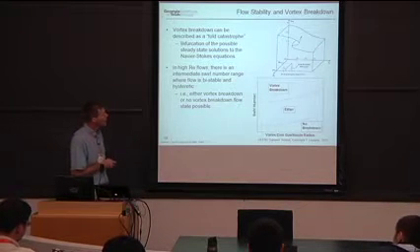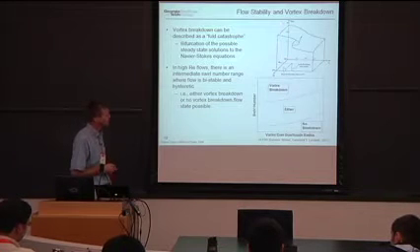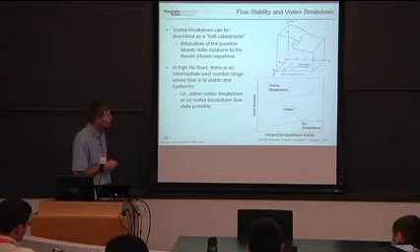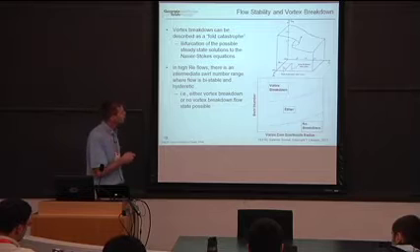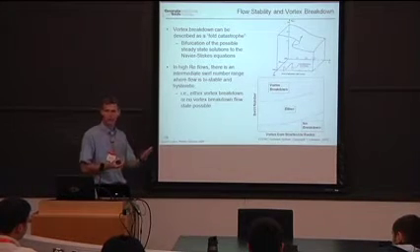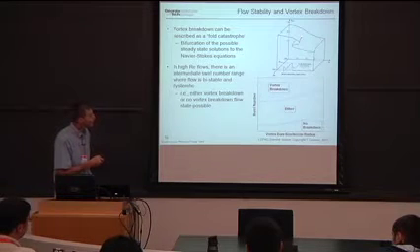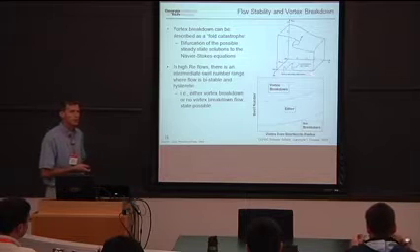The y-axis denotes the magnitude of the maximum reverse flow velocity. This axis denotes the swirl number. This axis denotes the Reynolds number. And so at low Reynolds numbers, what you get is this nice, smooth, monotonic relationship between reverse flow velocity and swirl number, right? But right at that critical Reynolds number, you get this fold that develops in the flow, all right? So what does that mean?